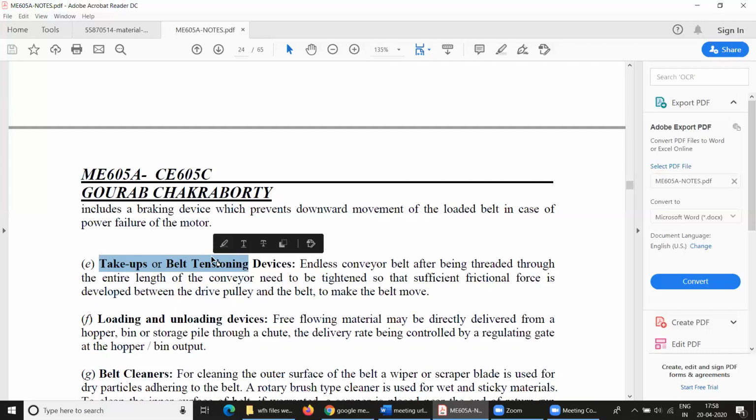In gravity take-up, the tail end pulley is mounted on a movable carriage, which is pulled backwards along the length of the conveyor by a vertically hanging counterweight connected through the steel rope and deflecting pulleys. In an alternate design, the return side of the belt passes by the bottom of a counter-loaded deflector roll, which is free to move down to keep up the belt tension.